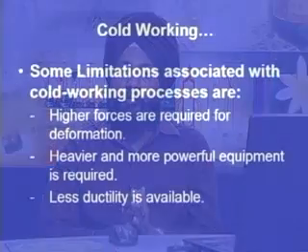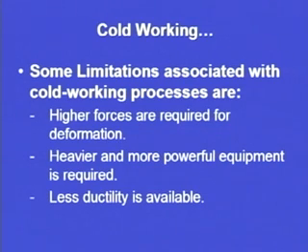So, the machine should also fit into the domain of these, avoiding the vibrations and avoiding the fatigue type of fractures. So, whenever we are going to make use of a cold working operation, higher forces are going to be encountered, and the machine that we are going to use for cold working should be able to sustain those kinds of forces. Then heavier and more powerful equipment is required. Already in the first point it has been explained that heavier and more powerful equipment is required in case of